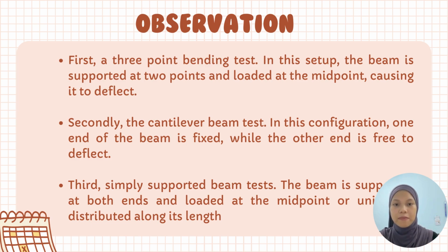Secondly, the cantilever beam test. In this configuration, one end of the beam is fixed, while the other end is free to deflect. Third, simply supported beam test. The beam is supported at both ends and loaded at the midpoint or uniformly distributed along its length.